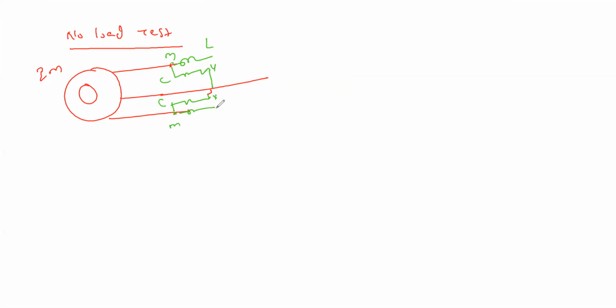This is B, DL is here. So this is the three-phase supply and we should also keep an ammeter. Normally we keep 3 ammeters, we'll take the average, and a voltmeter here now. I am supplying the induction motor, so for power measurement there is three-phase power, and we will get both powers. Power is P1 plus P2.